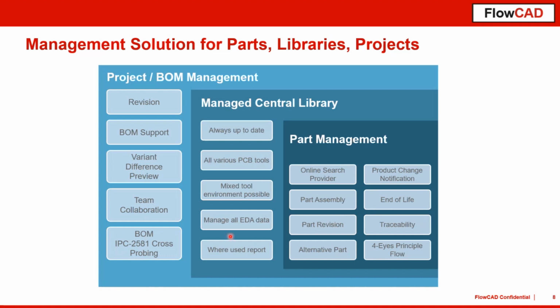And what is really interesting, there's a where-used report possibility. So you can have a look at what is used where. For example, what pad stack is used in what footprint, and also which parts are used in which different designs. This is really a nice thing, because in case something is wrong with the footprint or with the pad stack, you simply see where it is used and what you need to change to get rid of some problems.